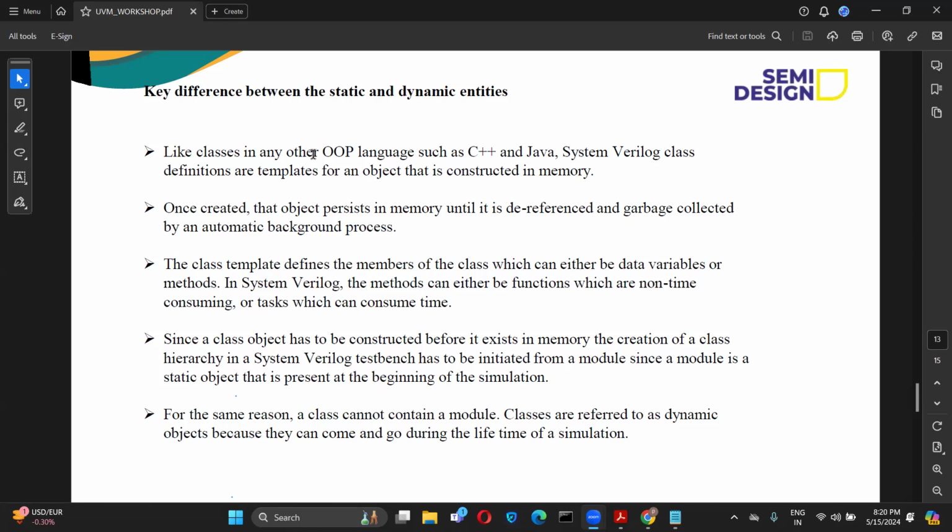Then I thought I would share one small code, as I had asked whether the class is standalone or not. She said no. Then how do we make it work? We have to use a module where we create the object, and then inside the initial begin use the properties of that class. If there is some task or function you want to use, you have to create an instance of the particular class where your task or function is, and then you can use that function through that instance.